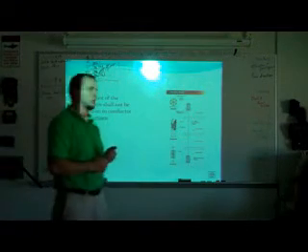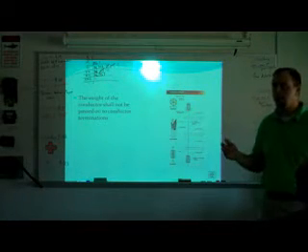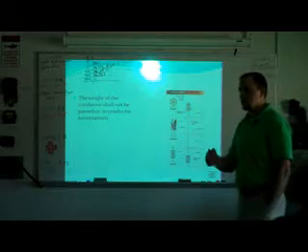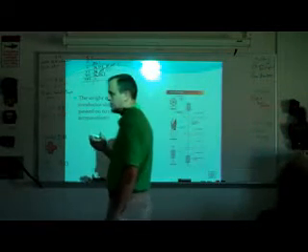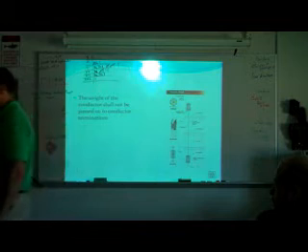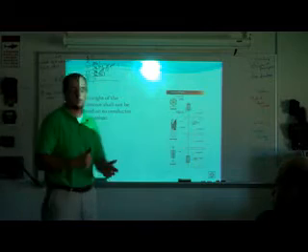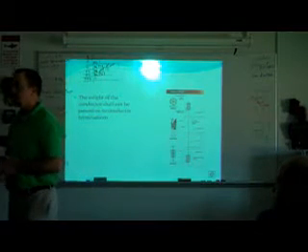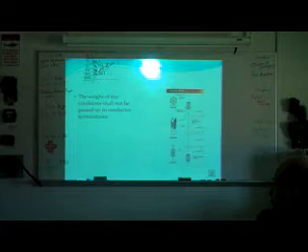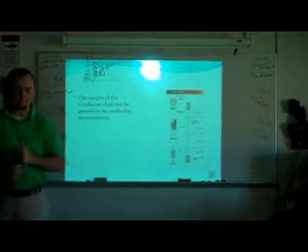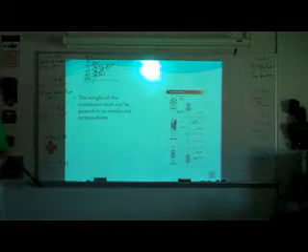Tell me this: what happens if I start to pull a conductor out of a terminal? The connection gets bad. What's that do to my circuit? It generates heat. Why does it generate more heat? It's forced to work harder, because there's more resistance. And eventually, if you do it, you'll end up pulling the wire out of the terminal, and then you have to call over a maintenance guy and say, hey, my push button station is not working. Well, yeah, you pulled the wires out.